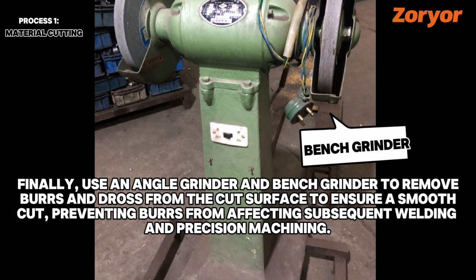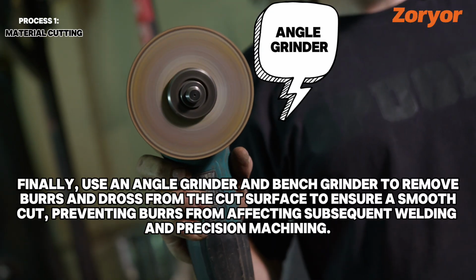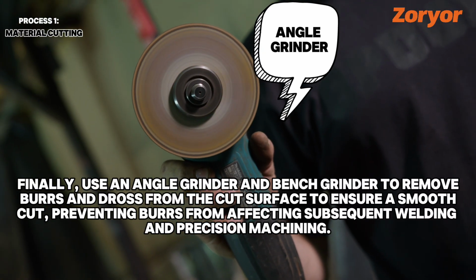Finally, use an angle grinder and bench grinder to remove burrs and dross from the cut surface to ensure a smooth cut, preventing burrs from affecting subsequent welding and precision machining.